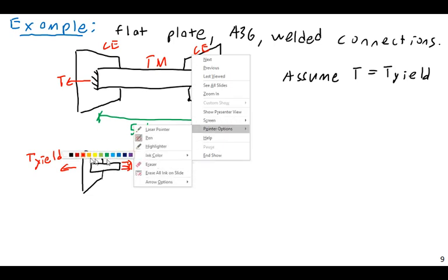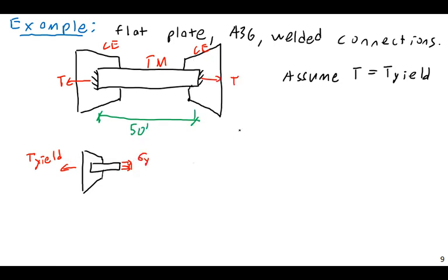Okay. The real point of this is that I want to see what kind of deformation yielding actually looks like. How much deformation does this actually produce, even on a 50-foot long member? So epsilon y is going to be equal to L_f minus L_0. Just like we compared in lecture 1, the difference between engineering strain and real strain, we're using engineering strain here, over L naught. So this is essentially delta L over 50 feet.